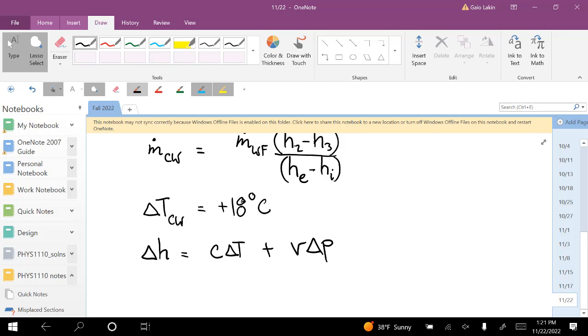The working fluid we have written is isobaric. Is the cooling fluid also isobaric? Right, we made that assumption. It seems like that probably is true. We don't know anything about the pressure, so there's no way we could fill that term out. I might have to get back to you on that one, but let's just assume that was also isobaric. Okay, it makes sense.